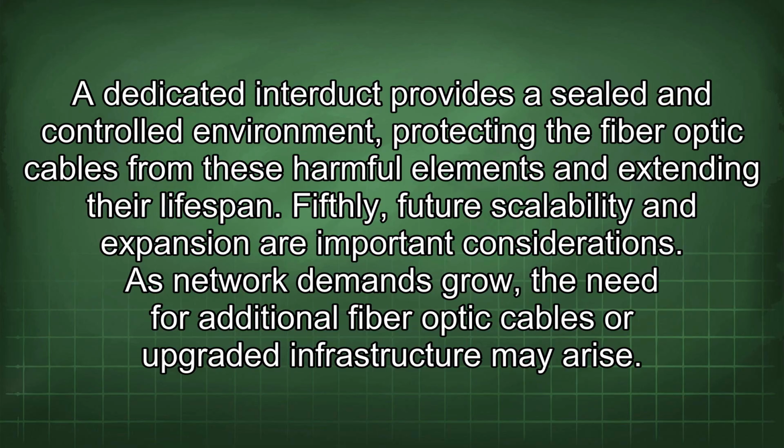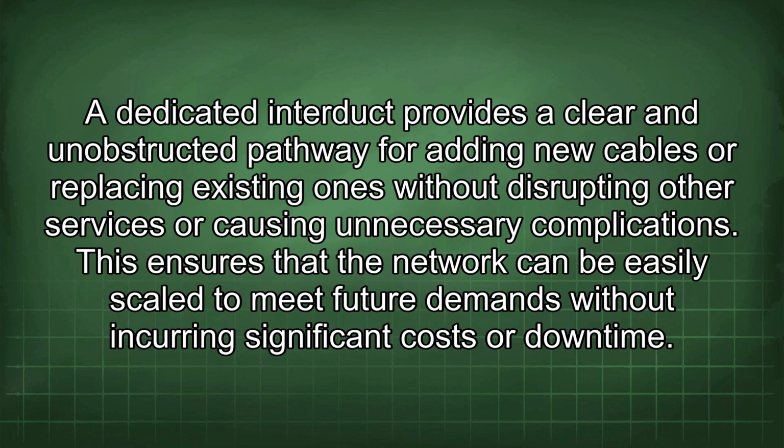As network demands grow, the need for additional fiber optic cables or upgraded infrastructure may arise. A dedicated interduct provides a clear and unobstructed pathway for adding new cables or replacing existing ones without disrupting other services or causing unnecessary complications. This ensures that the network can be easily scaled to meet future demands without incurring significant costs or downtime.